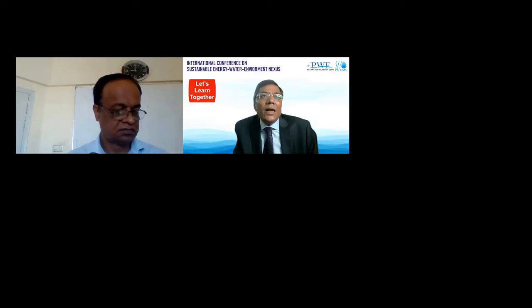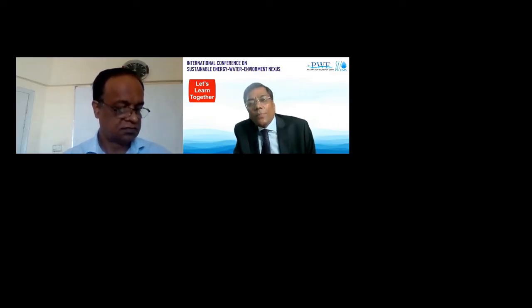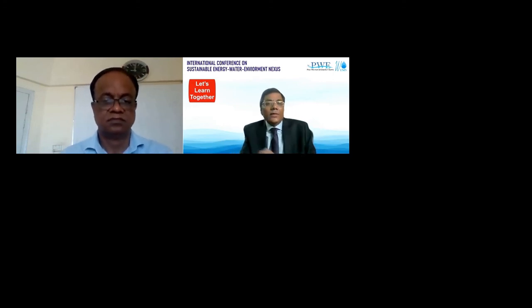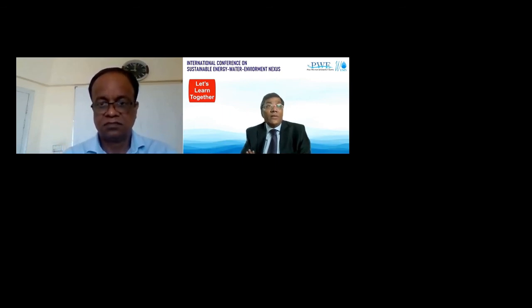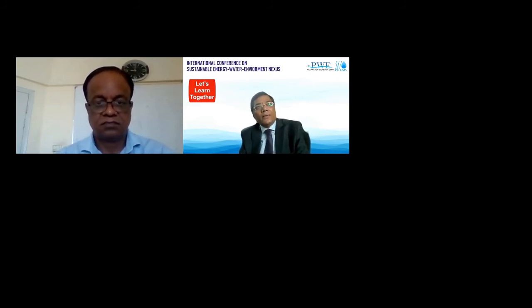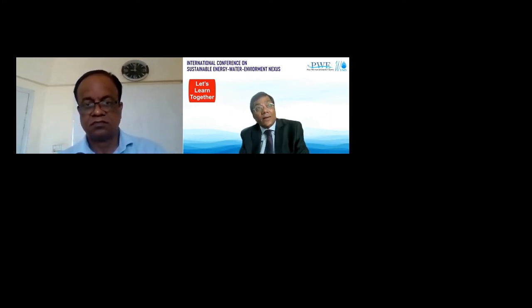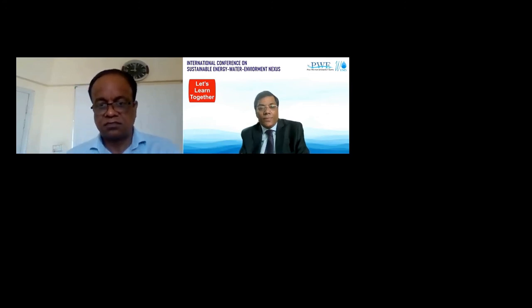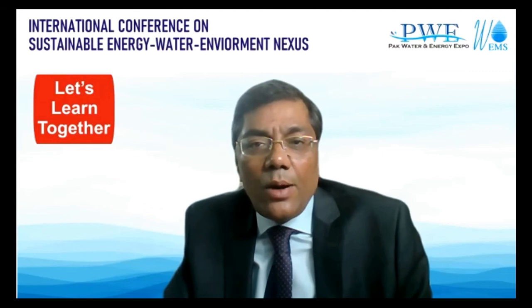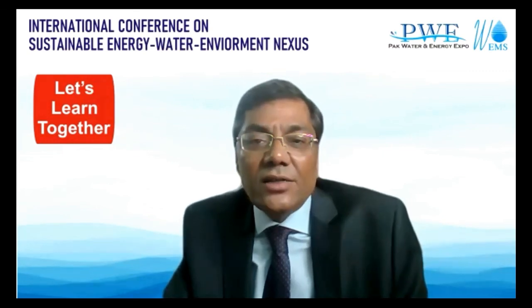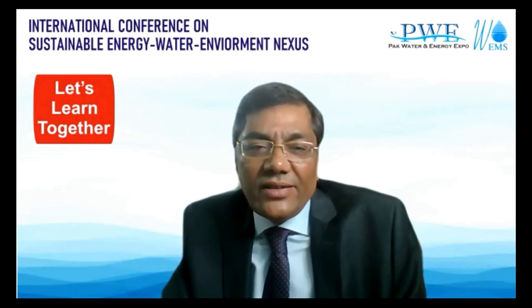I rank the conventional technology at the top, because with conventional technology we cannot afford much capital cost, and the operating cost is low. When we go for MBR technology, there is a huge capital cost, and every 5 to 7 years you have to replace the MBR membranes. To me, the best technology, especially in Pakistan and the current scenario where there is no problem of land and operating cost will be low, is the conventional activated sludge process.